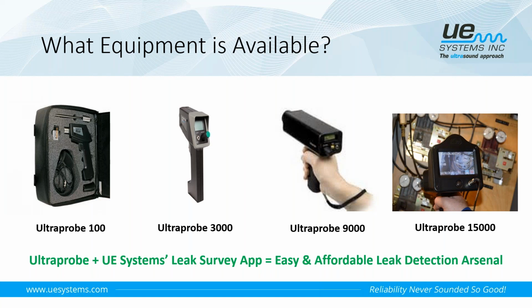If you look at these 4 models, though, you pair them, well, at least the 3000, the 9000, and the 15000, you pair those with our leak survey app that we're going to talk about. That's a free app that's available for download in the App Store or Google Play. So you take your UltraProbe, you take that leak survey app, and it becomes a very easy and affordable way to do a compressed air leak survey in your facility. Other than maybe some leak tags, those are the only 2 things that you would need to go out and perform a compressed air leak survey in your facility.